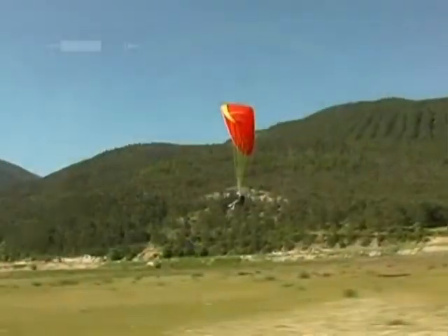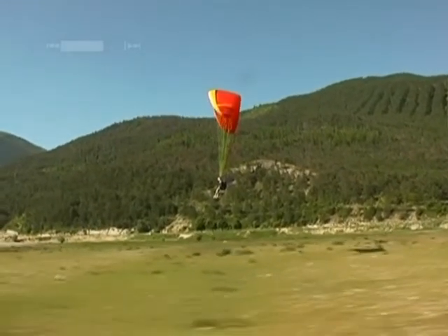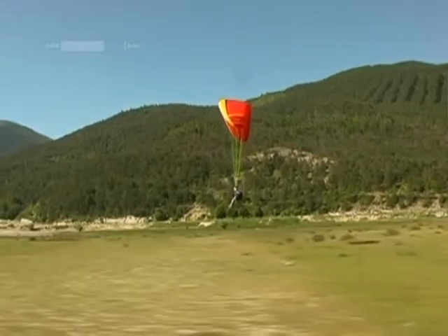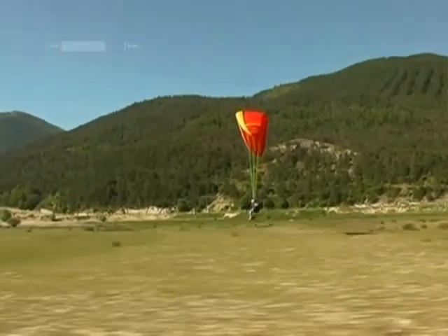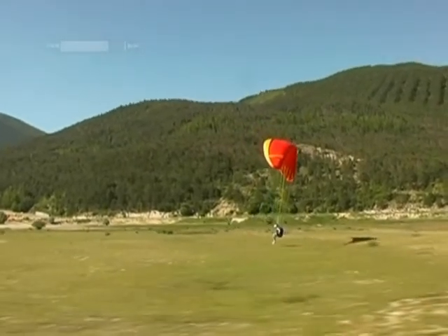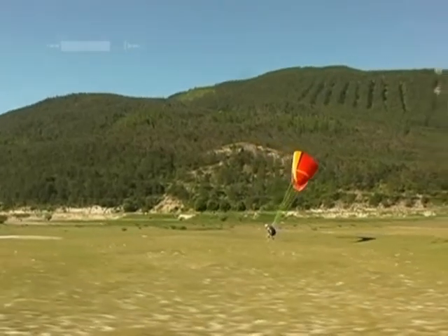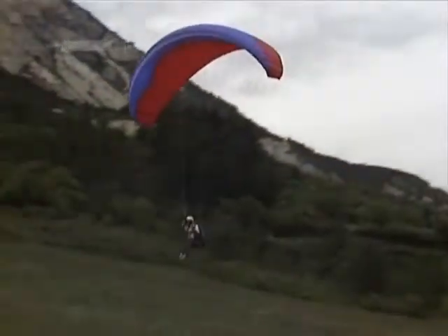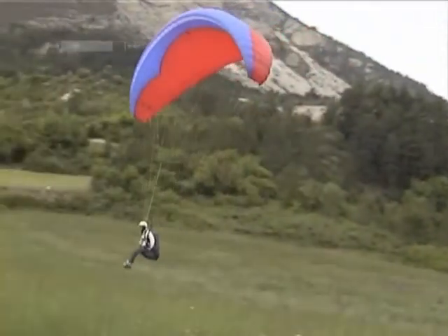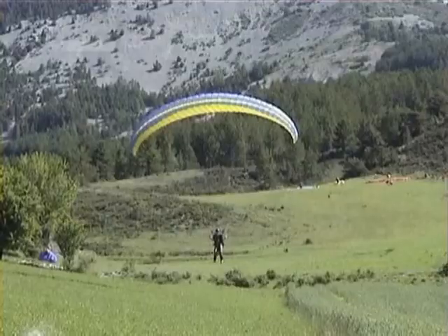In order to land safely, the pilot must reduce his airspeed and ground speed to a minimum. This is done by applying both brakes fully. This is called the flare. The flare is initiated 2 to 3 meters above the ground. This switch makes the wing pull out and produces a flare right before touchdown. An instructor will tell you when to make this switch by radio during your first flights.